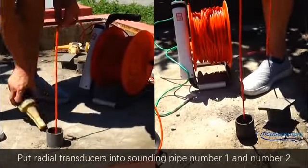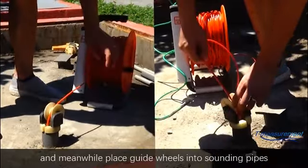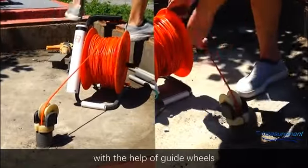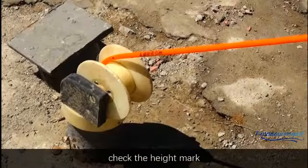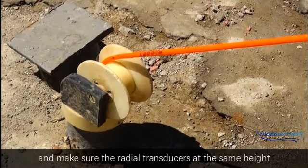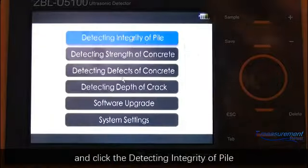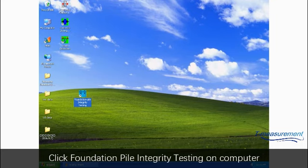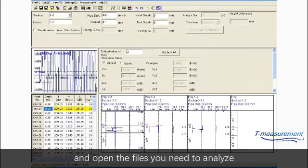Put a radio transducer into sounding pipe number 1 and number 2, and meanwhile place the guide wheel into the sounding pipes. With the help of the guide wheel, put the radio transducer into the sounding pipe, check the height mark, and make sure the radio transducers are at the same height. Connect the host and radio transducers and click Data Analysis. Click Foundation Pile Integrity Testing on the computer and open the files you need to analyze.